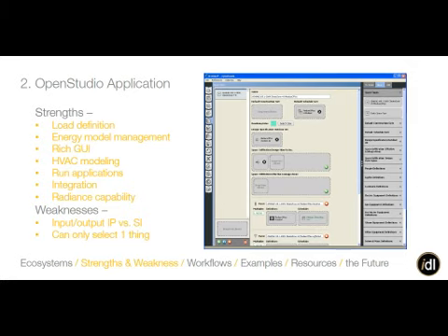One of the weaknesses of the OpenStudio application is that you can change between IP and SI inputs, but you can only output in metric. You can convert all of that to IP if you're in text mode, but it's interesting because you sacrifice a little bit of flexibility by having this front-end wrapper. You can't access the one object that would allow you to convert everything to IP. That's a little bit frustrating, because if I really want to output in IP and not have to convert it, then we have to open up the back end a little bit, which isn't a big deal, but it's just one extra step in that workflow. I imagine they'll fix that in the following versions, but they haven't yet. And who made this? The Department of Energy. And they did it in metric.